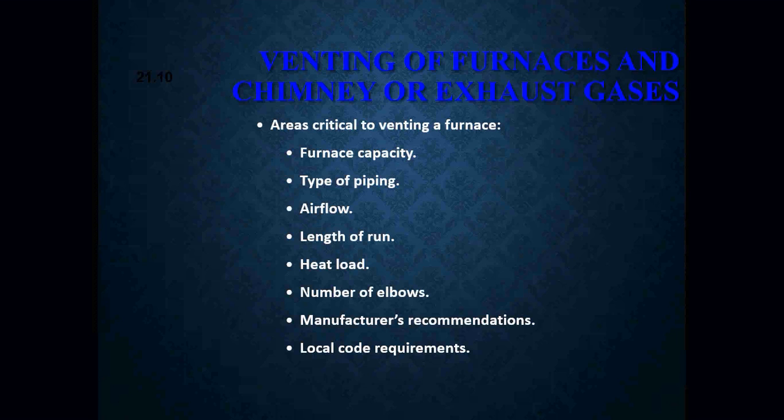Venting of your furnaces, chimneys, or exhausts, you have several different areas that you need to pay attention to when it comes to venting a furnace. For mostly, as you see here, you have your furnace capacity. We need to know the type of piping. We need to know the airflow, how long our chimney exhaust run is going to be. We need to know the heat load of the entire building. We need to know how many elbows that we're going to need to make that connection. We also need to make sure we follow your manufacturer's recommendations and also all of your local code requirements.